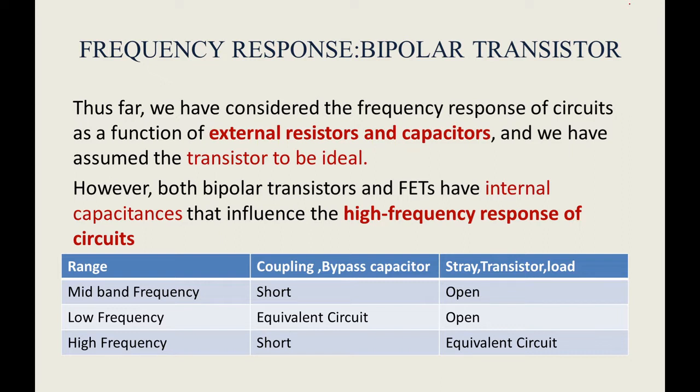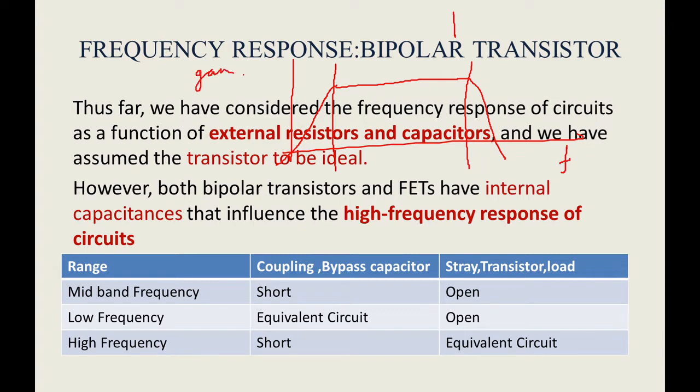So in the low frequency part, let me draw the graph. See, this is your frequency response. So here you will be drawing a frequency response like this. This is the low frequency and this is your higher frequency. This is frequency versus gain. See, in the low frequency there is a limitation of gain. This is called a roll-off. Similarly, here in the higher frequency it is also called a roll-off.